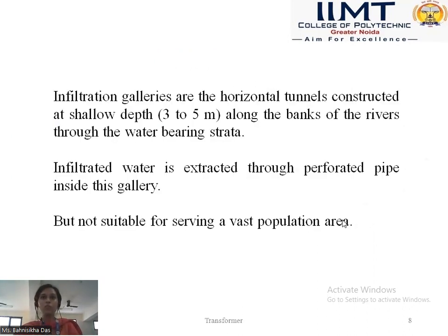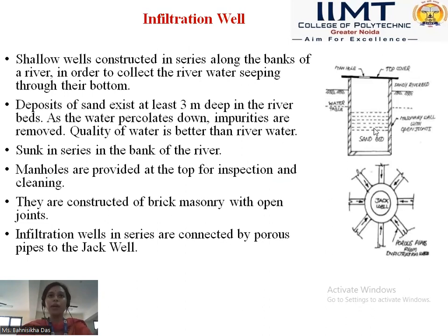However, in case of an infiltration well, the wells are covered at the top and open at the bottom, and because these wells are constructed along the bank of the river, the river water will seep, and because of the head difference or pressure difference, the water will enter into this well.